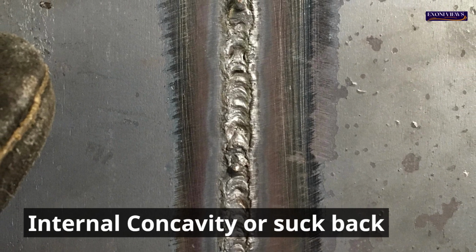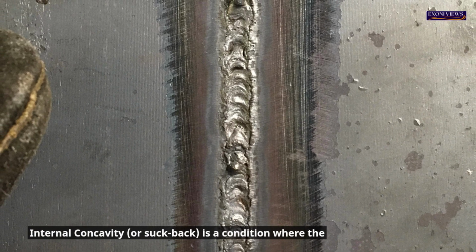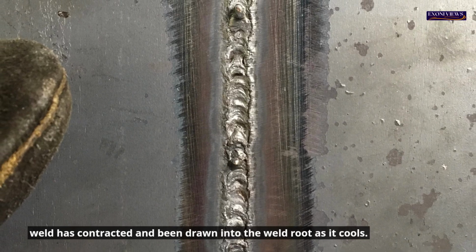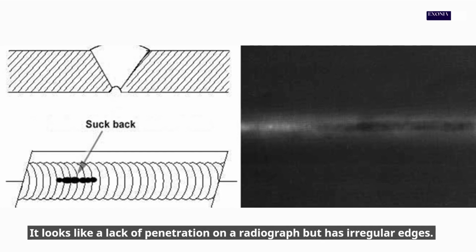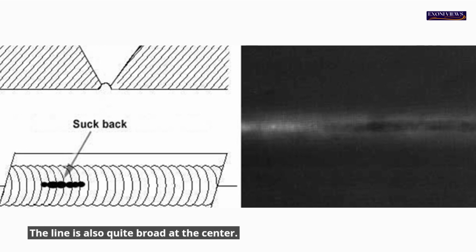Internal concavity or suckback. Internal concavity, or suckback, is a condition where the weld has contracted and been drawn into the weld root as it cools. It looks like a lack of penetration on a radiograph but has irregular edges. The line is also quite broad at the center.